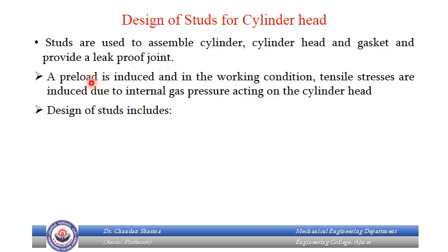A preload is induced, as we know that for vessels subjected to internal pressure, we always use studs or bolts, and those are preloaded bolts or preloaded studs. A certain compressive stress is induced so that when they encounter actual working conditions, there is always some preload which helps them retain the leak proof joint.